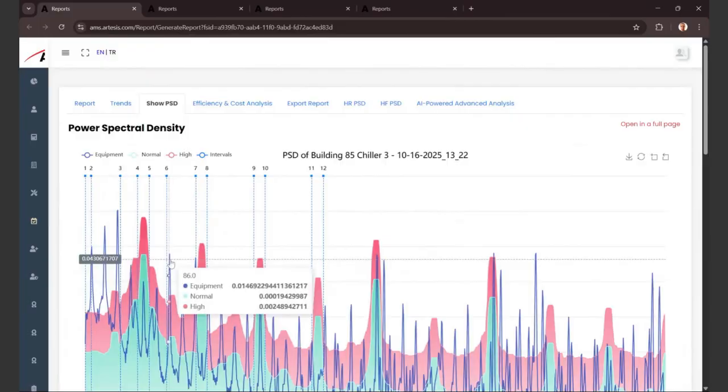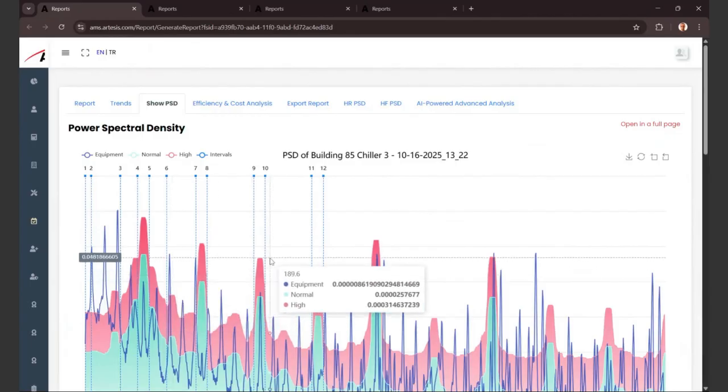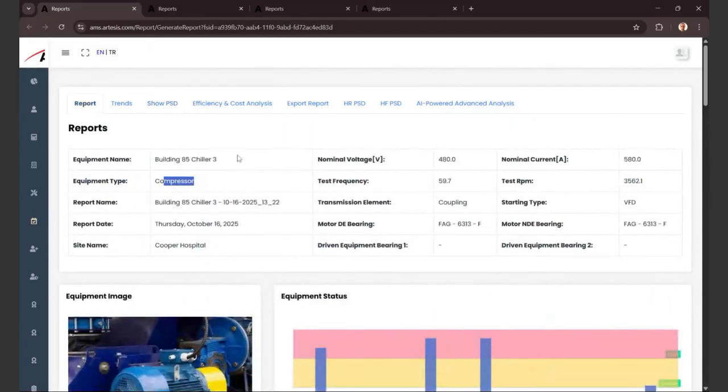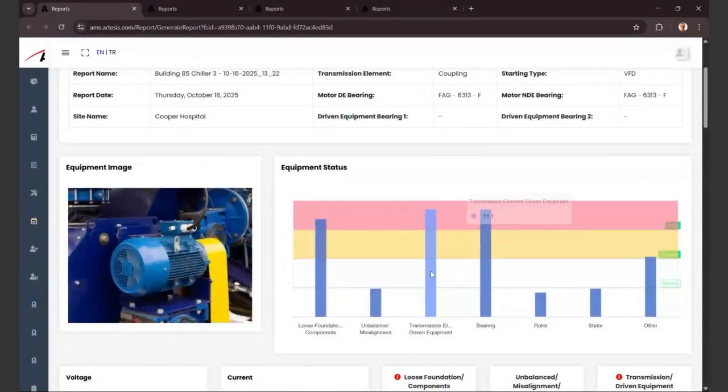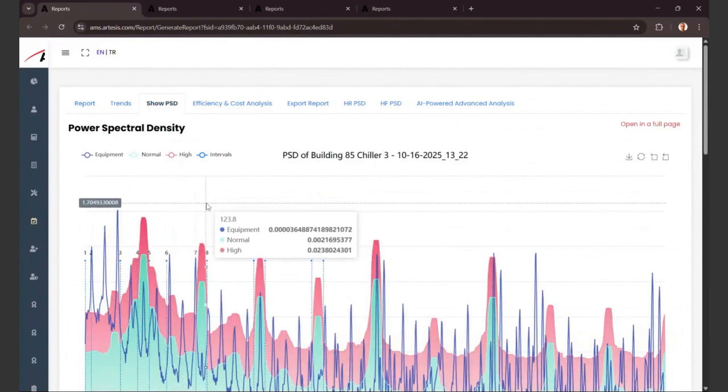okay, that's likely misalignment or unbalance. And if you see subsynchronous or non-synchronous frequencies, again, you have bearing issues or other issues, rotor stator. So each one tells you a story, but somebody has to do it. In this case, of course, you have a coupling. So this transmission means actually the problem is coming from the compressor side. So I know all this from my expertise.